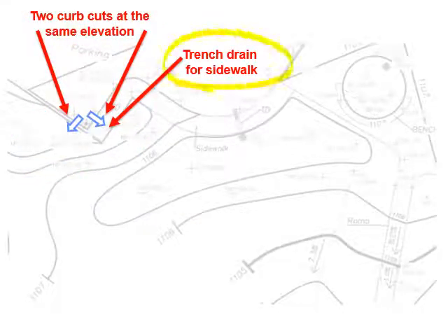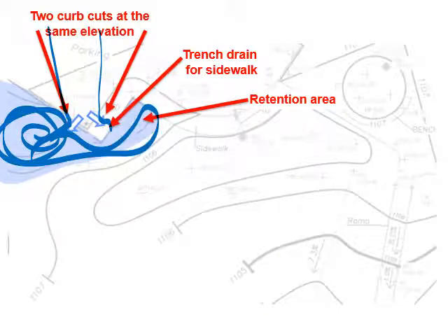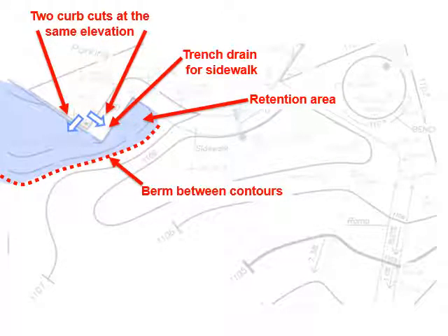We of course then can have a trench drain that's connected to one of those curb cuts. That gets the water all the way across the sidewalk. So water flows down into the system. The system starts to fill up until eventually it blocks off the curb cuts. Should be familiar by now.